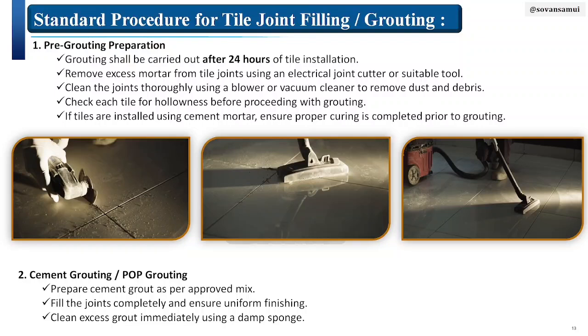Next point is cement grouting and POP grouting. Grouting can be done with cement or POP, and epoxy also. If we are using cement, then prepare the cement grout as per the approved mix. Fill the joint completely and ensure uniform finishing, and clean excess grout immediately using a damp sponge.